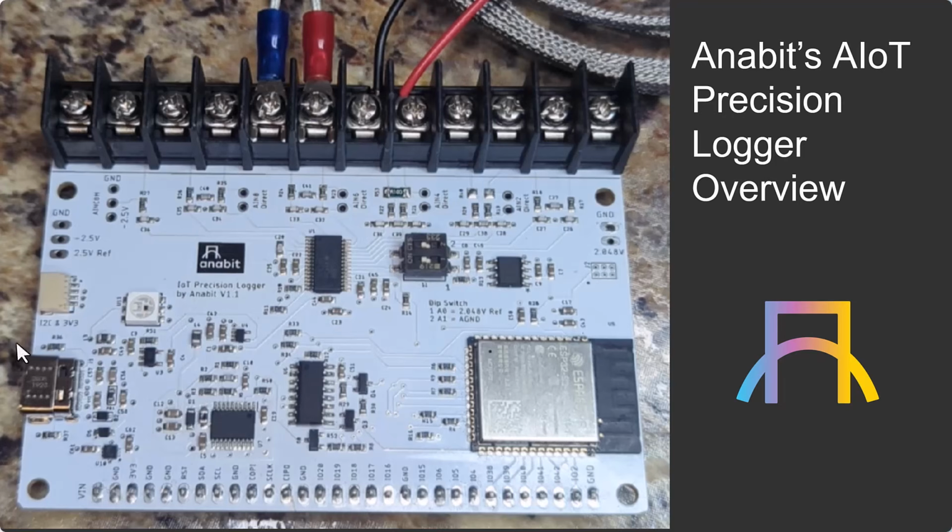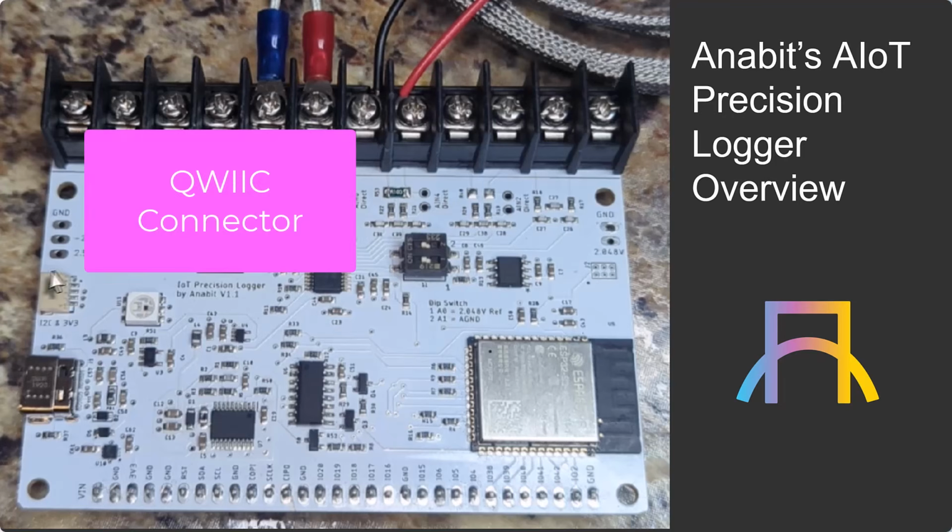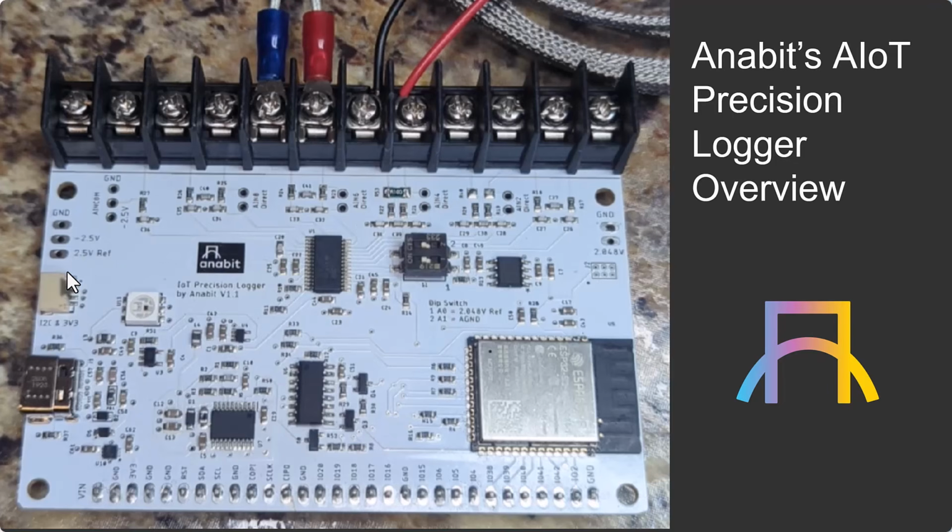The design is powered by 5 volts, so you can power it from the USB-C connector. You can also power it from some of these pins down here. The USB-C connector also allows you to program the ESP32 with just a USB cable, and you can do UART communication with the ESP32. We have one of the quick connectors. This was invented by SparkFun. So this provides I2C, 3.3 volts, and ground. So you can integrate sensors from other makers, actuators, things like that, all without doing any soldering. We have an RGB LED on board, which we'll see in the demo.